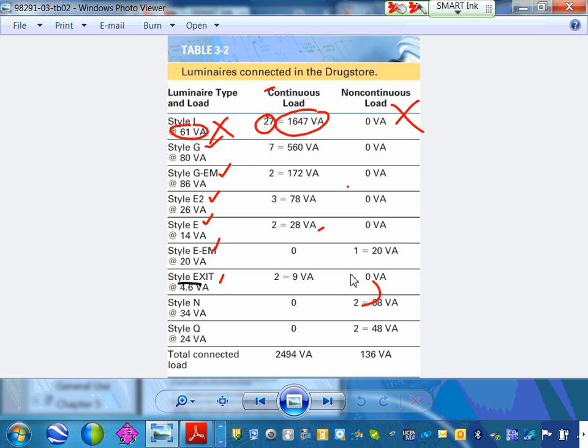That's what you guys are going to do for our commercial project. You're going to take the volt-amps of all your fixtures from the manufacturer, compare them to the 3.5 volt-amps, and choose what? The larger. And I can tell you from now, anybody can guess what the larger would be? The code book. Almost always, because you have to meet the energy code. You can't just go put any fixture.